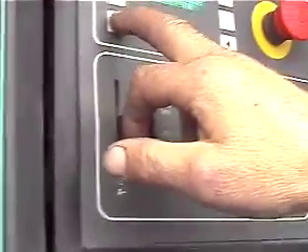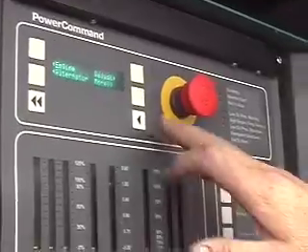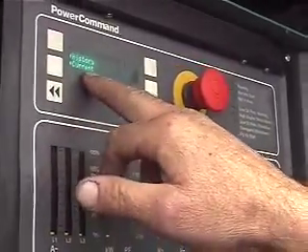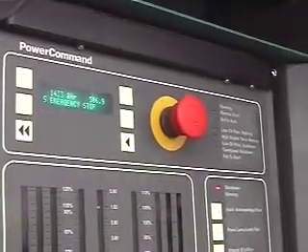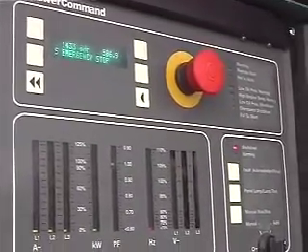I'm Fran. So, first off, the screen's dead. To wake up the screen, we're going to push one of either the double arrows or the single arrows. And then we want to find out what this shutdown is. We're going to push more. We're going to go to faults, and then we're going to go to this one that says current. Somebody hit the emergency stop and didn't reset it.